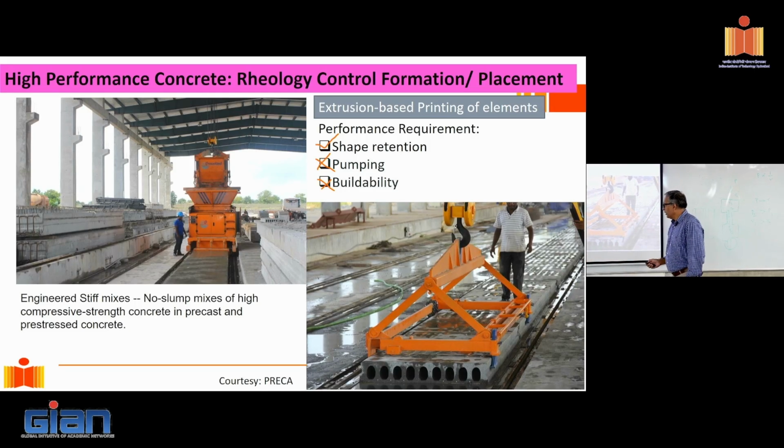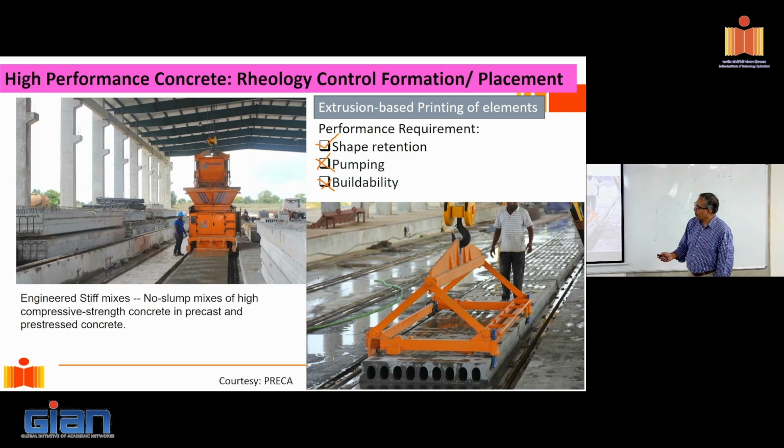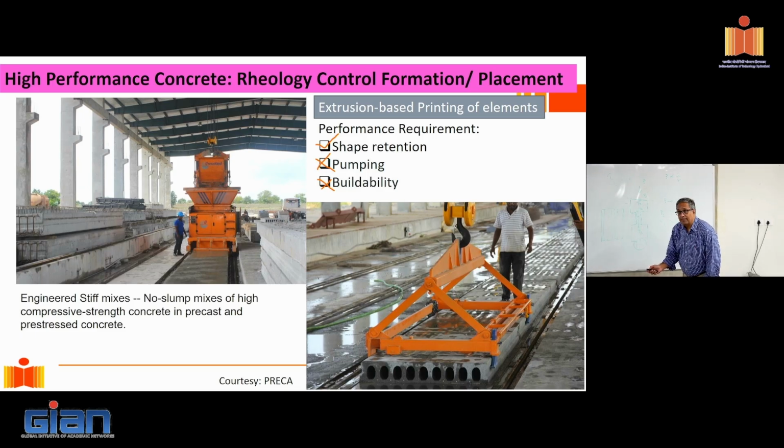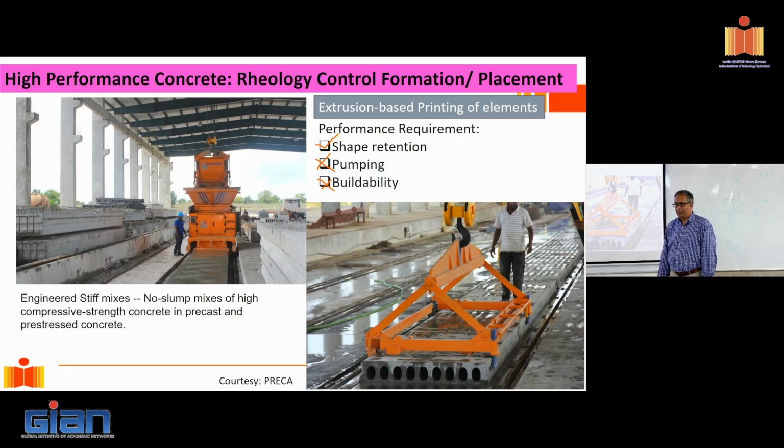If you look at the forming of these hollow core slabs, if you've ever seen it, the way it's done is they dump concrete onto this. It's a slip former. As it's moving along, it extrudes. I don't know if you can make out here. It extrudes a hollow core slab with these openings. Okay, so the concrete comes out with the openings and it keeps its shape.